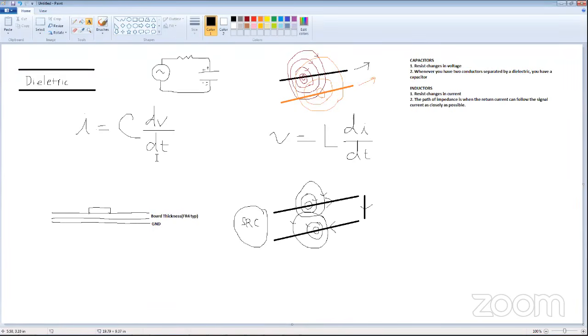Okay. And then this right here is your signal trace. And the behavior of these types of topologies is well understood. So that's why he recommended microstrip. So you're going to know how much coupling you can have to nearby traces. In something like this, those rules of thumb apply very well. So if you have two traces that are the same thickness and you don't want them to couple, then you just separate them by that amount.